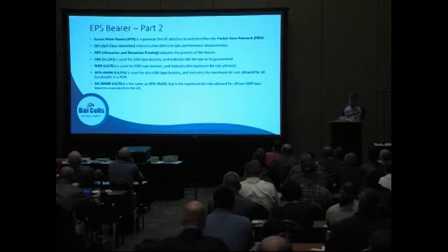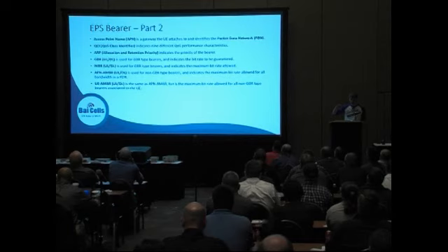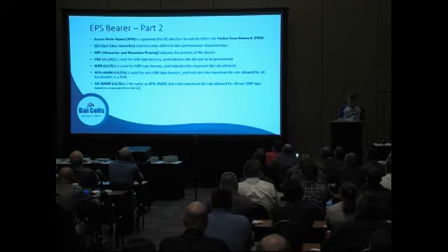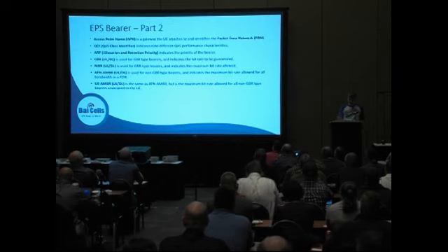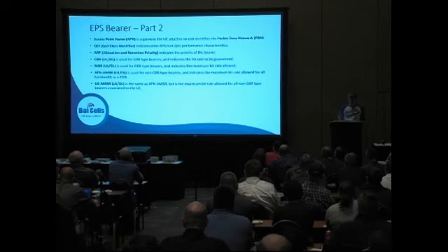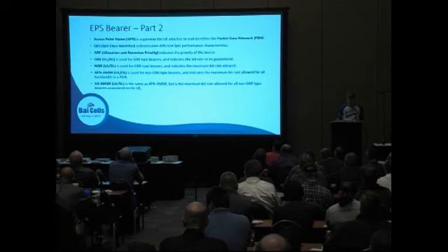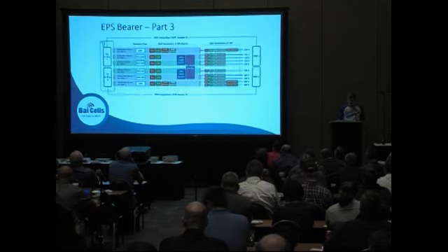With the beta software, if you look at the last term here, UE AMBR, this is the maximum bit rate allowed between all of the non-guaranteed bit rate bearers. So with the beta software, right now, you're able to actually rate limit customers. What this does is, with the bearer, it assigns a UE AMBR. And this is how we're able to currently rate limit with the Baicells equipment.